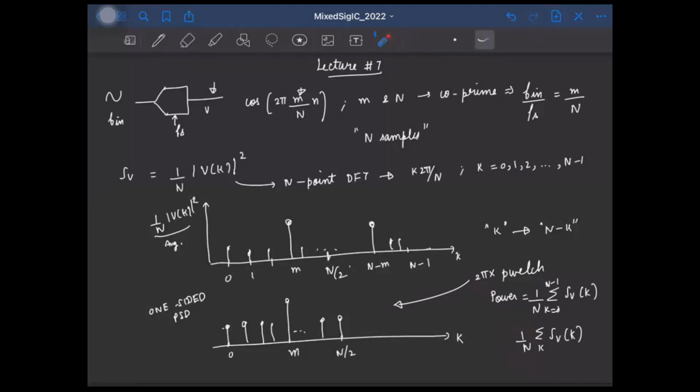We are trying to compute the ratio of the signal power to the quantization noise power. So even if you miss the scaling factors, the ratio does not change. But you should be careful when computing the absolute power of the signal; in that case, you need to include the scaling factors properly.